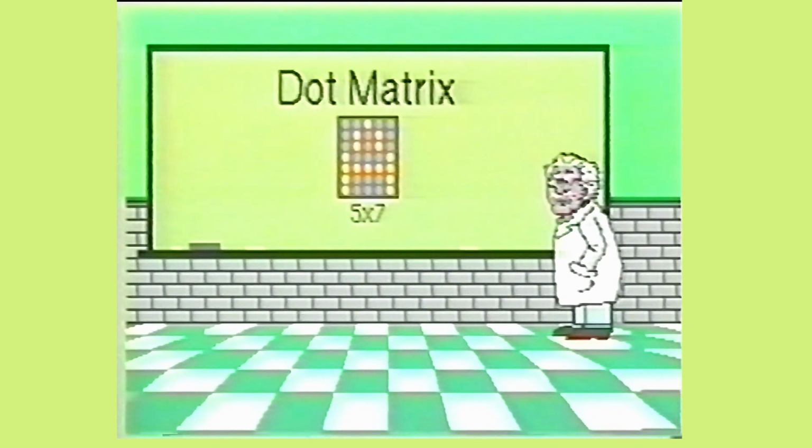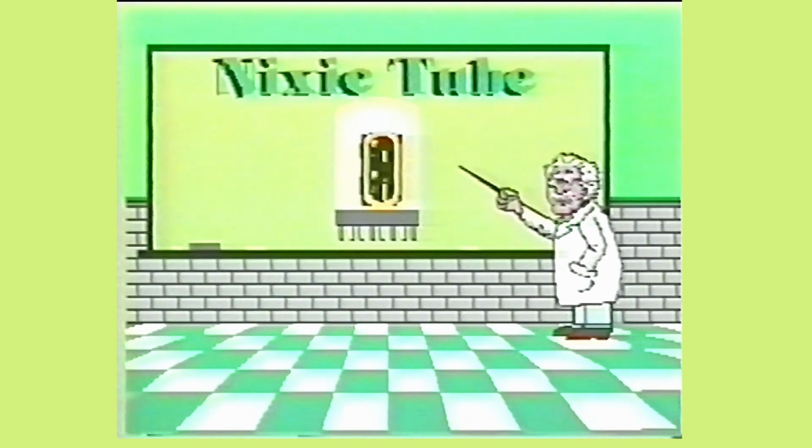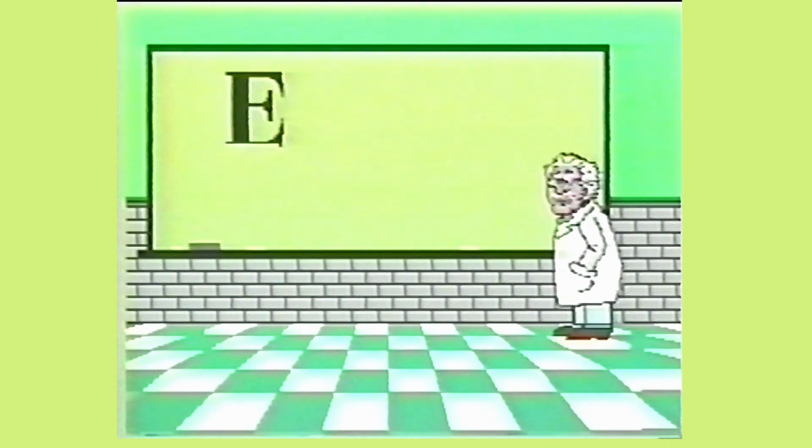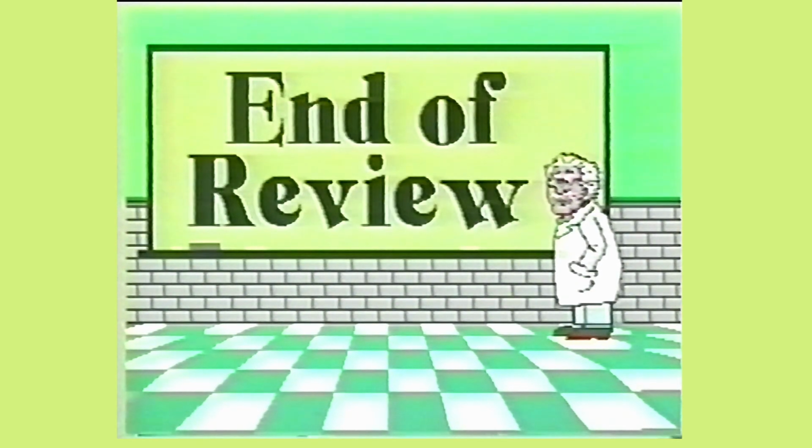Another common display device is the dot matrix display. The dot matrix display is a rectangular array of light-emitting diodes consisting of a 5x7 or 7x9 pattern. The Nixie tube is a gas-filled cold cathode vacuum tube in which the filaments are formed into the shape of decimal numbers 0 through 9. Nixie tubes are no longer as popular as they once were. This concludes review number 4.